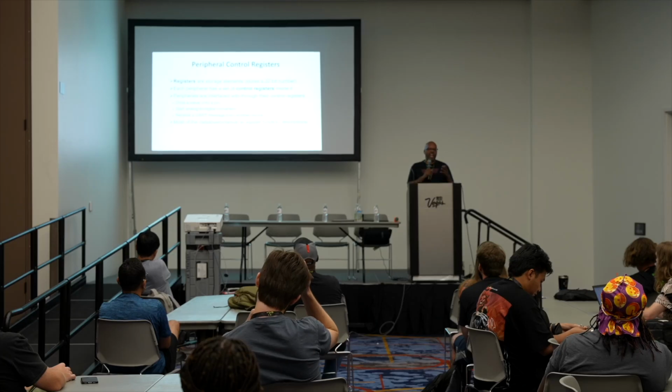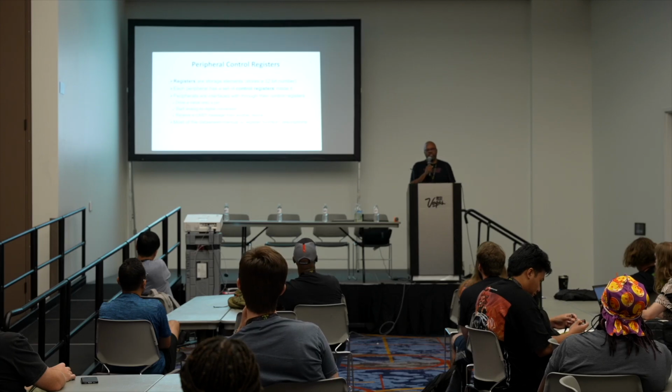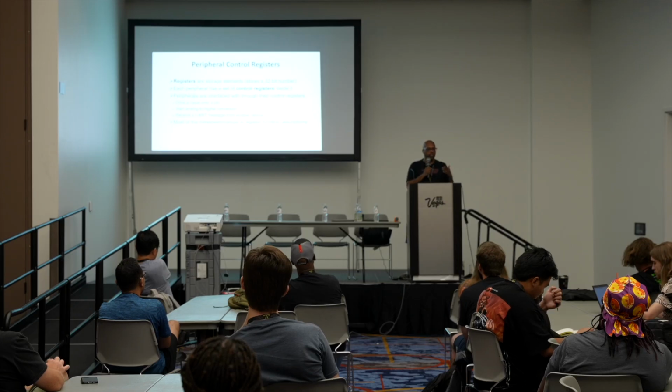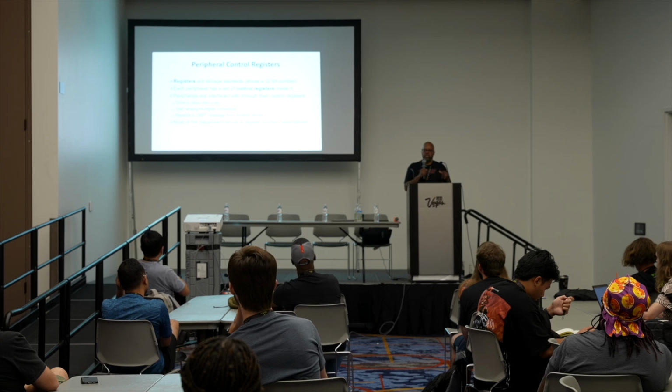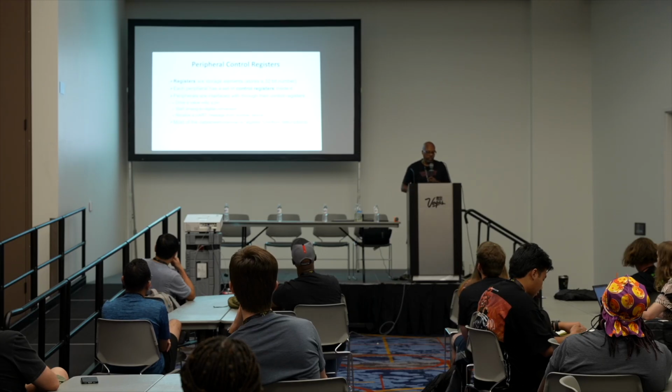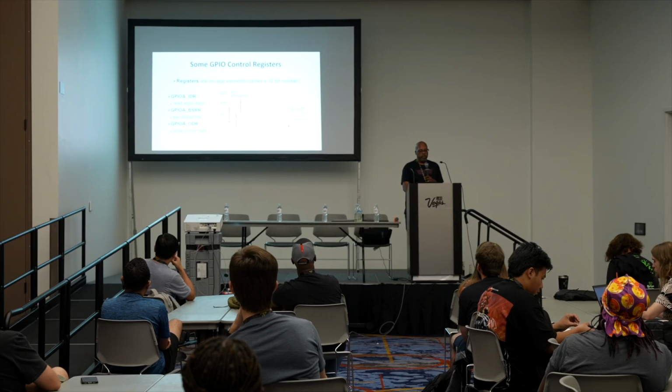A lot of my students get sick of this because you're looking at all these tedious details. Oh, I see, bit 5 of this register makes this start, and bit 6 puts it in this mode, and all this. That's why the data sheet is like 1,700 pages long. So that's how you control them, through these registers, whether you want to drive a value onto a pin, or do A to D conversion, or UART, or whatever.